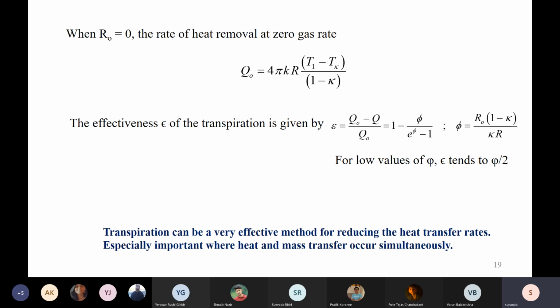If you recall the chemical reactor problem which we solved in yesterday's class, there was a preheating of the reactants entering the reaction zone. The preheating was due to a flow of conductive heat in the reverse direction of the convective flow of the reactants into the reactor. So conduction and convection operating in the reverse direction can cause an amount of heat flow to the system.